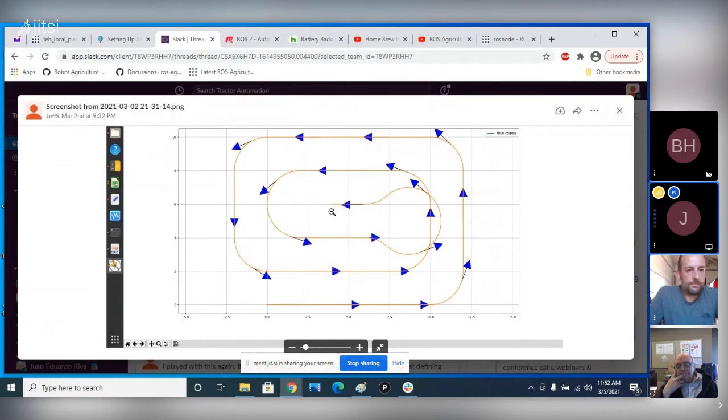But if you do this in a big enough field, it doesn't do that to you. So you just have to keep track as your area to work with gets smaller and smaller. All of a sudden it does this, where it generates that light bulb curve. And one more interesting fact: if I were coming this direction here, and I specified this same point, but going the other direction, it will actually come out like this. It'll draw a curve, come back, and hit this same point and come right back going the same direction. And it figures all that out for you. You don't have to figure that out. All you're concerned about is the spacing between these horizontal rows here. And as long as that spacing matches the radius, then the vertical spacing will also match the whole thing.